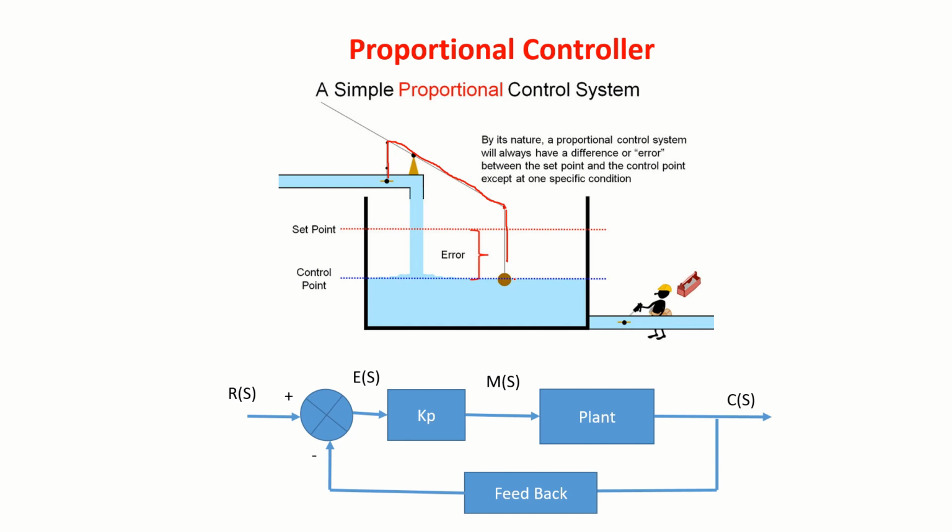You see here, as the water level rises, the float will rise, moving this up. So about this hinge point, it will move like this, opening the valve, right?